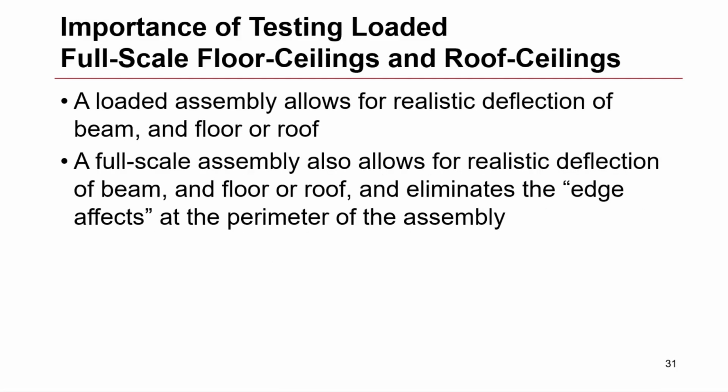And once again, the concept of loading that assembly allows for realistic deflection of both the beam and also the general floor or roof area, the floor roof deck, in other words. And likewise, the use of a full-scale assembly allows again for that realistic deflection of the beam, floor or roof, and also eliminates the edge effect at the perimeter of that assembly. So once again, it's critical that we test these assemblies loaded as required by the standard on a full-scale basis.